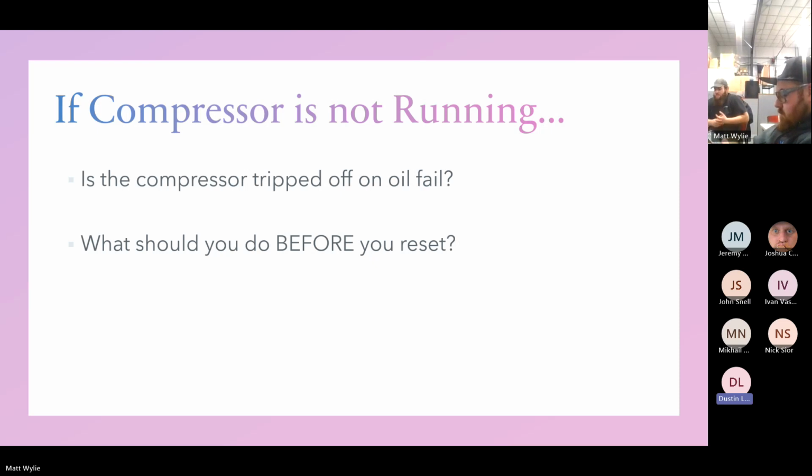You basically have to start at your suction header and check your superheat there, which we've talked about in some of the previous classes for the guys that were able to attend. What's the minimum superheat at a compressor? 35, 40. 20. 35, 40 is great, but Copeland, Bitzer, they don't want to see less than 20. When you get that low suction temp alarm at Costco, it's because it's looking at superheat. Low suction temp means your suction is too cold, which means your superheat is too low.